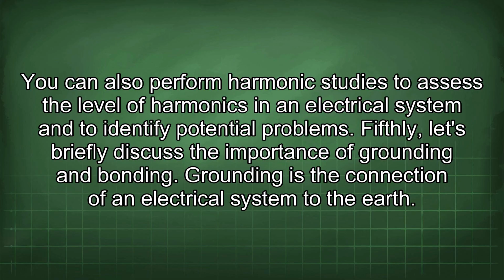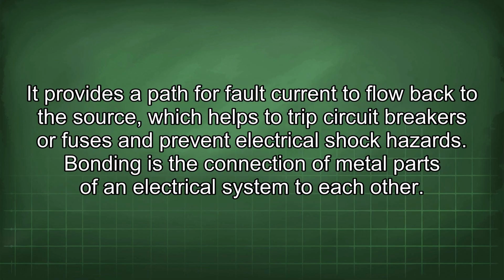Grounding is the connection of an electrical system to the earth. It provides a path for fault current to flow back to the source, which helps to trip circuit breakers or fuses and prevent electrical shock hazards.